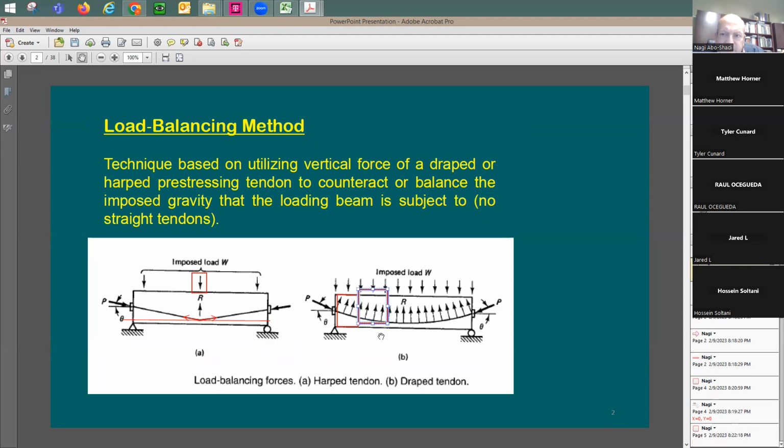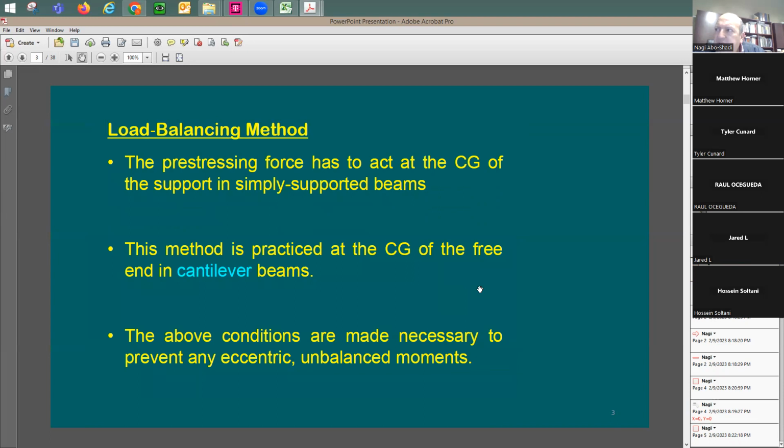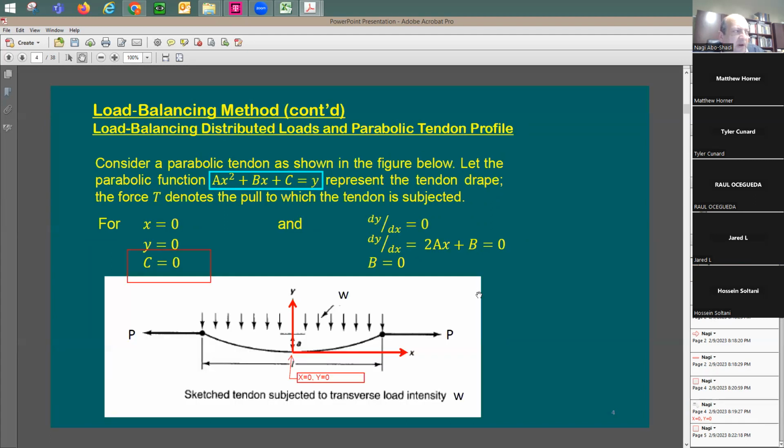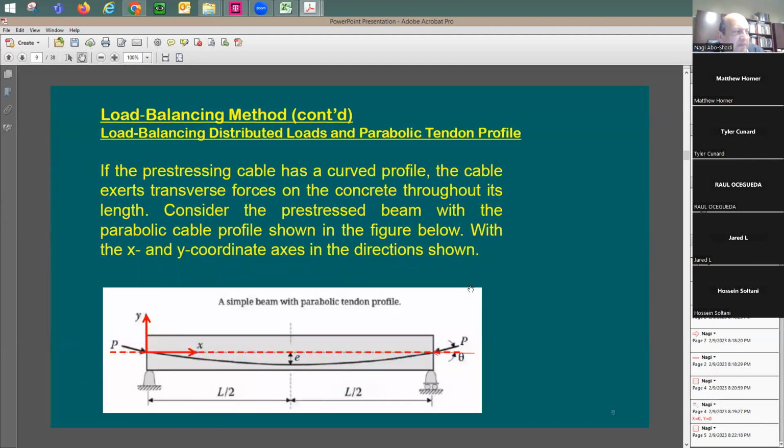It's causing shear, but in the other direction. It's going to be opposite to the applied shear. So actually it is opposite to the applied shear, which means it is helping the beam to resist the applied shear from the loading. So it's good action. It makes the shear stronger. So the shear equation that you used to see in the conventional concrete now is going to be different, and it's going to give you higher results for pre-stressed beams.